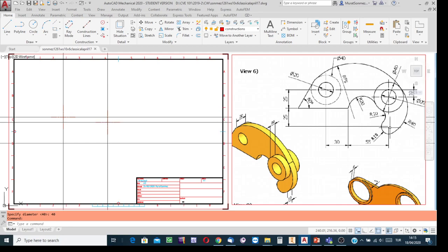So here there is no symmetry axis to show. If it were a full circle or semicircle, then I would say yes, create the axes of symmetry, but here no. Just keep it as a center point thanks to the existence of the intersecting transfer lines.